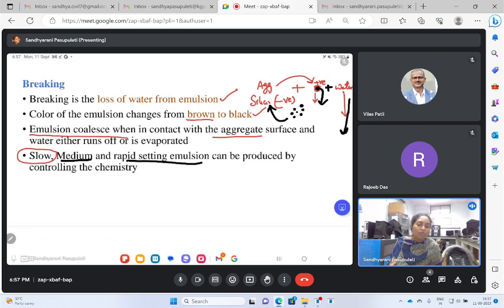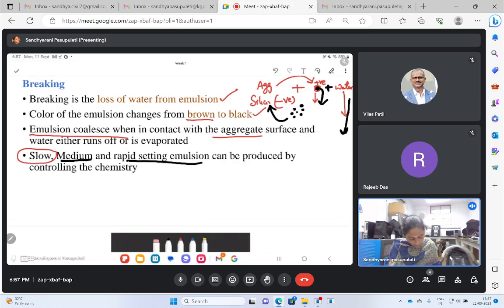Let us say you want to construct the different pavement layers very quickly, and you want to use this for a tack coat. What do we do? Let us say you already have a base bituminous mixture you placed. Upon this, you want to again place a binder course. These two are separate bituminous mixture courses only. So before even laying this binder course, you want to apply a layer that can provide a better contact between these two layers. Then you will actually spread the emulsion.